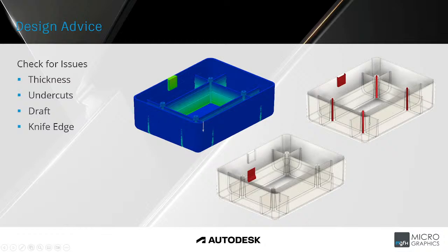Then we get to the design advice tool. This comes close to the end of the design process if you want to check for manufacturability of the component. With plastic parts, the thickness is a very important part of the molding process. We want to make sure that the thickness is as uniform as possible throughout the component. So we can check for issues such as component thickness.